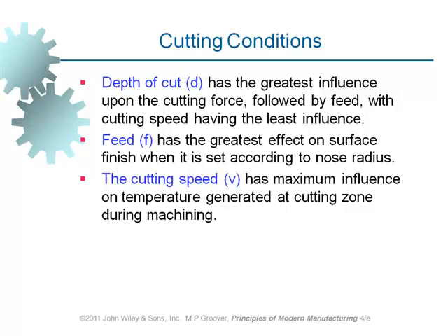For a given tool, the desired tool life is given by the manufacturer of the cutting tool. What is the highest cutting speed which gives us desired or designed tool life? That's the one. So 3 simple basic rules in order to decide each of these 3 machine parameters.